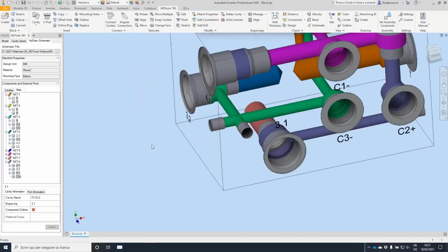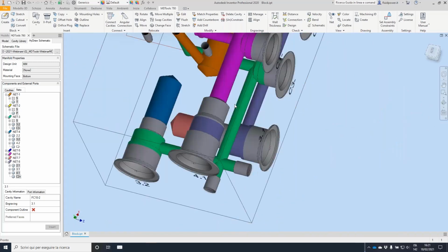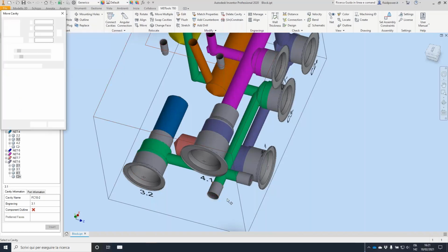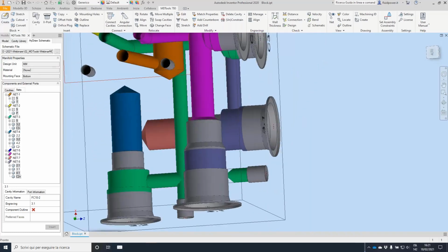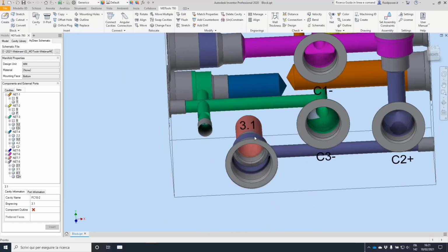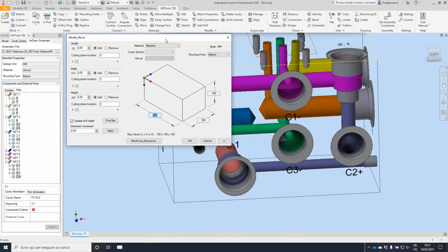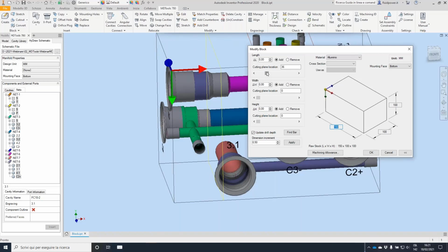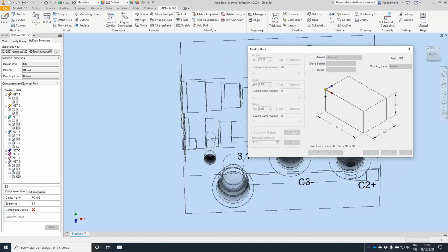Let's go. So here we have this net. I need to connect, so I may need to move this cavity in this direction. I want to connect these nets, so let me just remove some material. There is a command that allows us to remove material. On the length, maybe here, I want just to remove 10 millimeters. So this command will stretch the block.